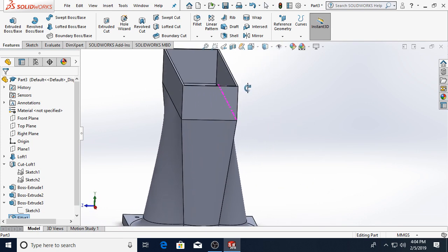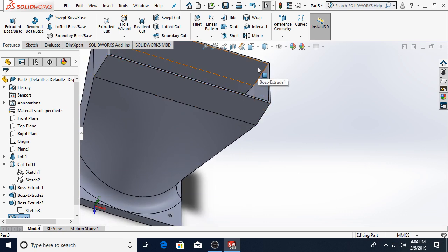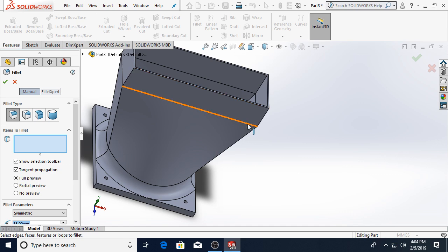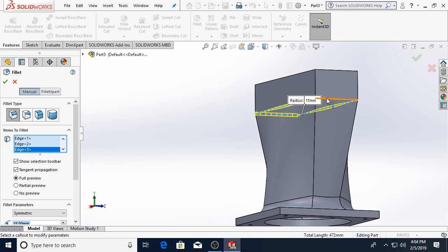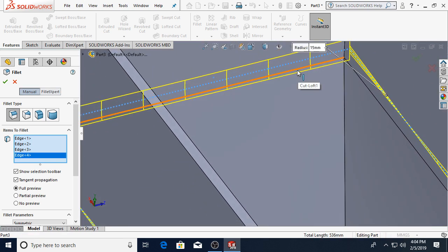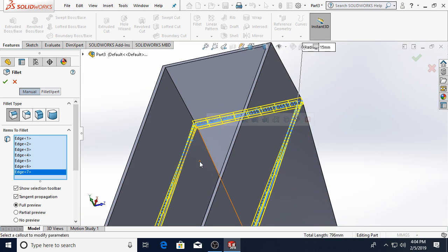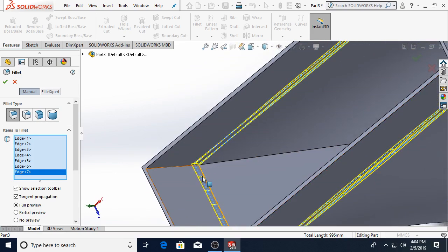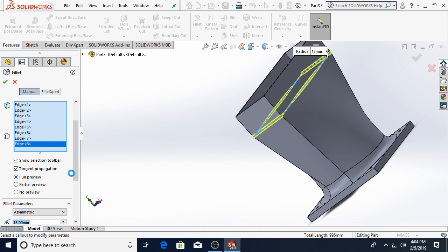Maybe I want the transition between this lofted shape and this linear extruded shape to be softer to try to minimize our losses. I could create a fillet on that edge just the same, and I could even create a fillet on the inside edge as well. If I keep these radii the same, then I don't have to worry about cutting off part of the material, and there we go. So by default, this was 10 millimeters.